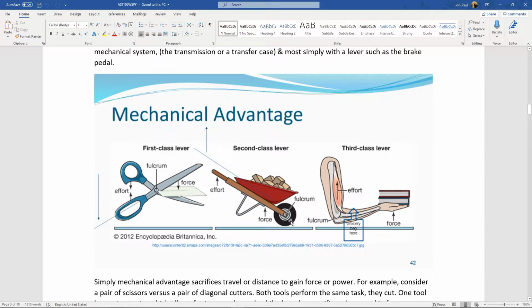car. That's going to be second class lever. We have a pivot point here where the clutch lever is mounted to the firewall. You push on the bottom of it where the pedal is, and it pushes the rod. Your brake pedal's the same way. It pushes the rod here in between the two of you. And then this is a great example here. This end where your foot is travels a much greater distance than this does, right? And the effect is that it multiplies the force. The force, Luke.